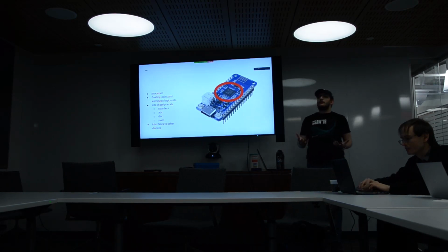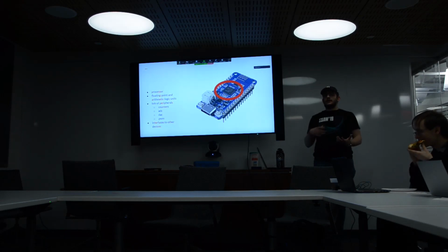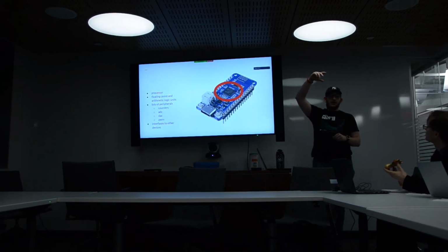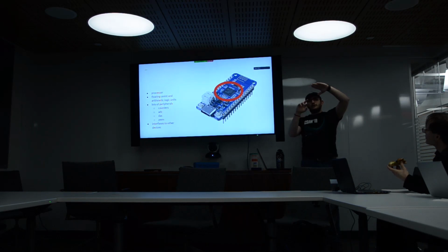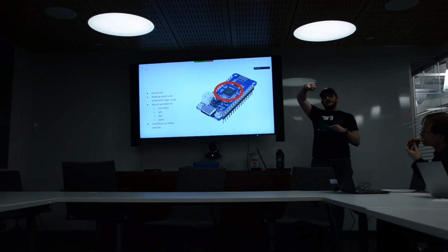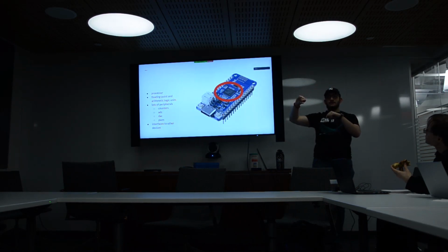The simplest analog sensor device is called a potentiometer, which is basically just a variable resistor. And the way that you would read one of those is you tie one end to the 5-volt pin, the other one to your ground, and then you use your analog to digital converter to measure the voltage on the wiper pin, which is actually going around a coil inside. And by measuring the potential difference between your high voltage and your middle voltage, you can figure out where the potentiometer is.